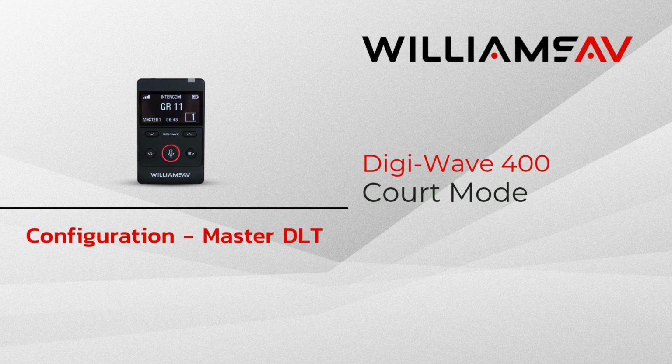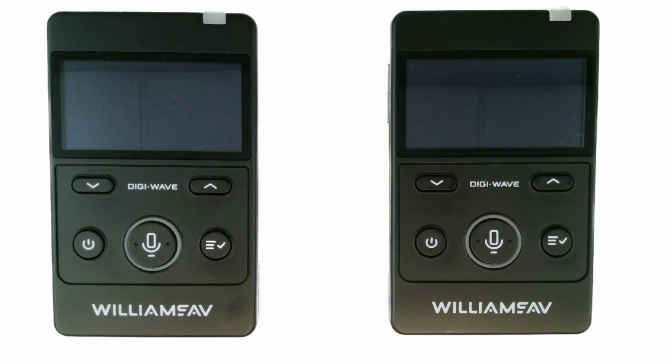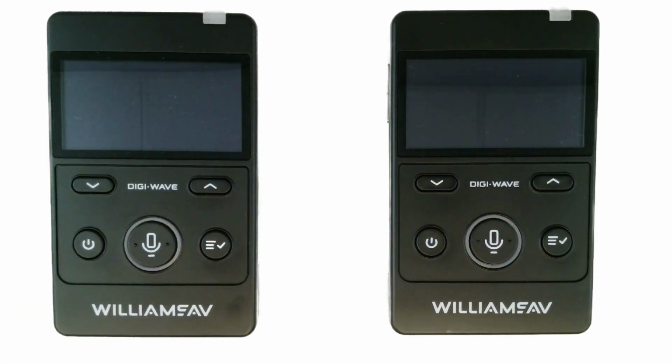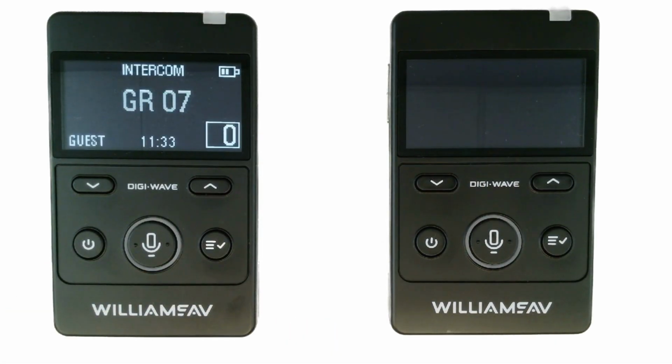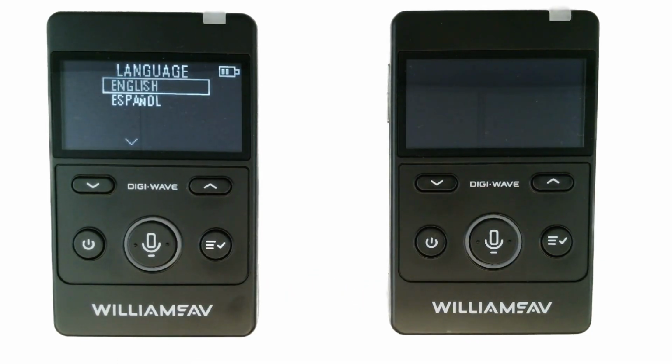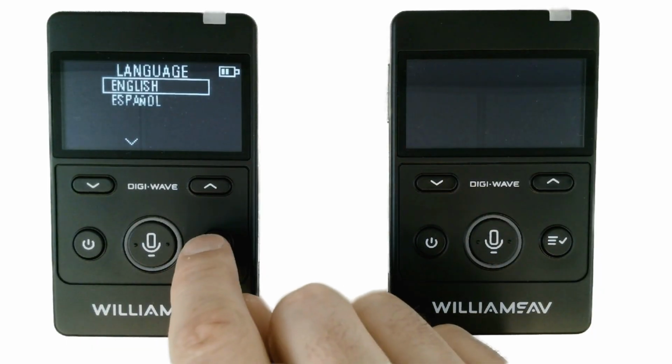Step 1. Powering on. To begin, press and hold the power button for 2 seconds to turn on the DLT 400. Step 2. Entering the settings menu. Once the device is on, press and hold the menu select button for 2 seconds. This will take you into the settings menu. Use the menu select button to scroll forward through the options. To go back, press the power button.